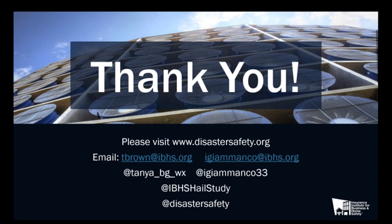We want to understand where it might make sense to have impact-resistant roofs, based on that frequency and severity of stones, and make sure it's an economical decision. If there's a location that's constantly getting, and I'll exaggerate, 5-inch hailstones, impact-resistant products are not designed to meet that. So we really want to focus on what areas could benefit from having these products in place.